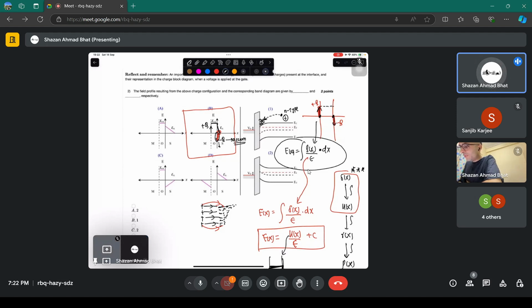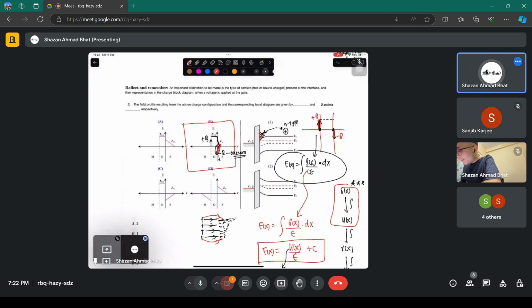Whenever you note this particular bending in the n-type, this acts like a well for the electrons, where the electrons can reside. They like to stay there because it's a region of lower electrostatic potential energy. They don't have to spend a lot of energy to stay at this place, because the electrostatic potential energy has gone down at this particular point. So it's a well for electrons.